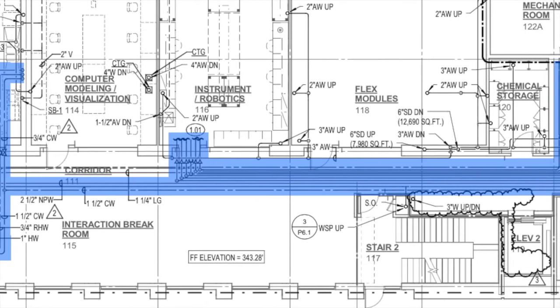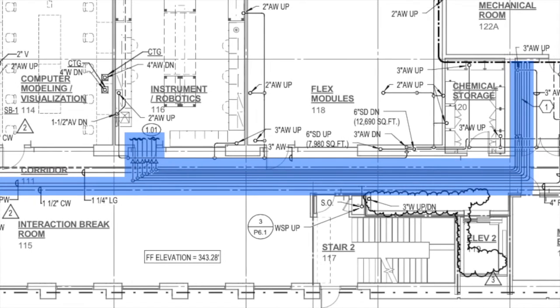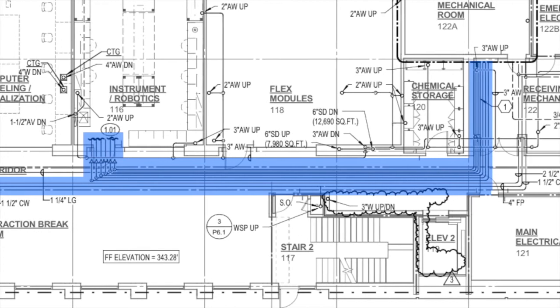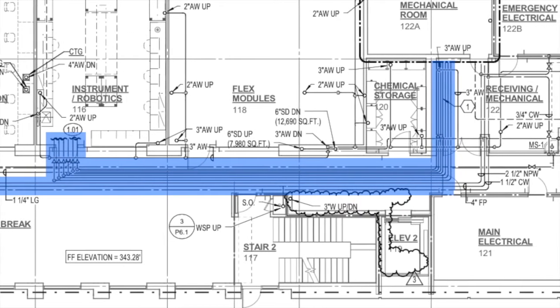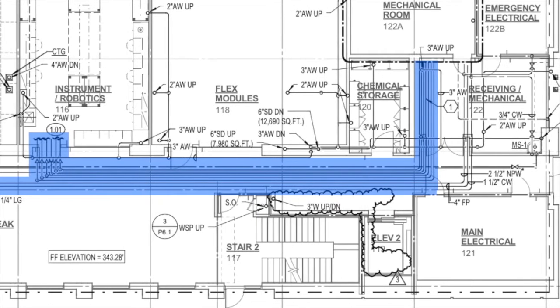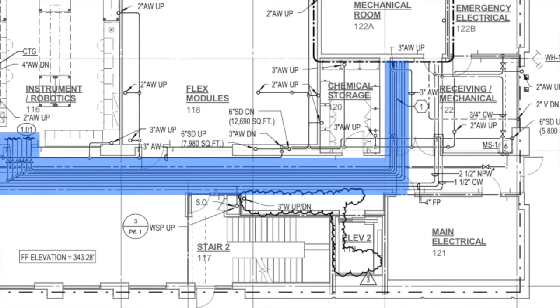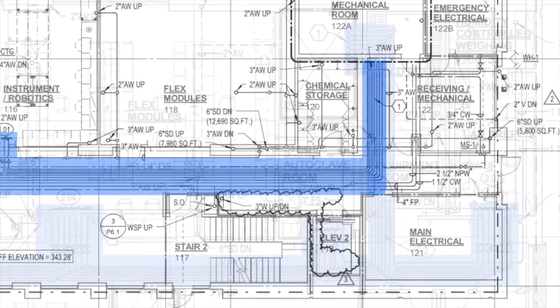The plumbing considered on the first floor can be seen highlighted in blue. These clusters include 1.5-inch cold water, 2-inch ventilation, 1-inch hot water, and acid waste. To each of these main outlets, 1 cold water, 1 ventilation, 1 hot water, and 1 waste has been taken to return back to the mechanical room.